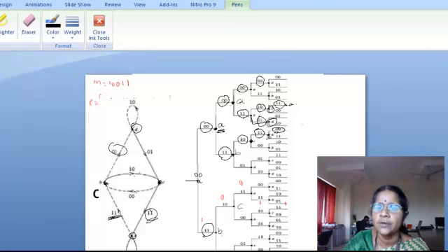So you go to state B and the output is 0 0. So you have to go like this throughout the code tree. You have the state diagram with you. To go up from any point of the tree, consider the input to be 0. To go down in the tree, take the input to be 1. Then find out what is the next state and the output from this state diagram and mention it in this code tree.